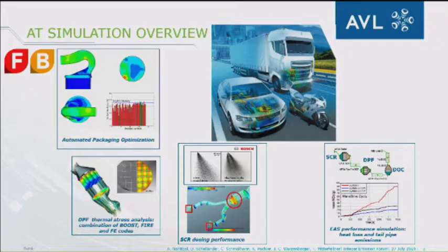In this case, the temperature can increase over the material limit, and it is also possible to check with the simulation tool whether there are scenarios when the regeneration temperature can reach above the limit. Next is the SCR dosing process, which we will talk about in more detail later on.